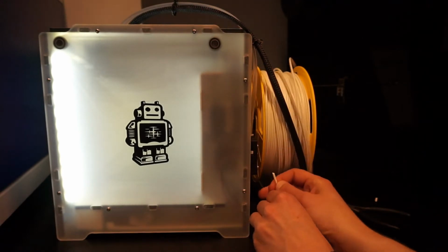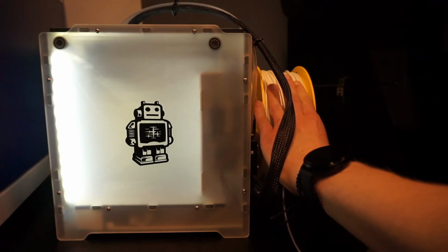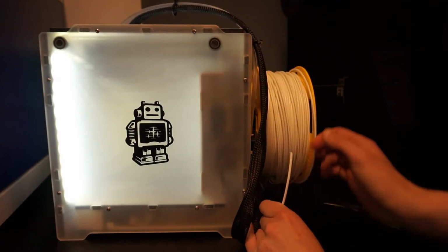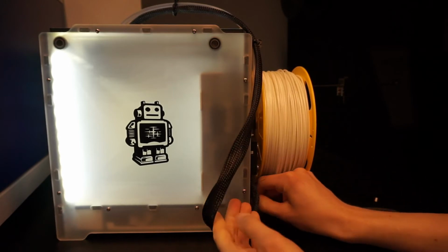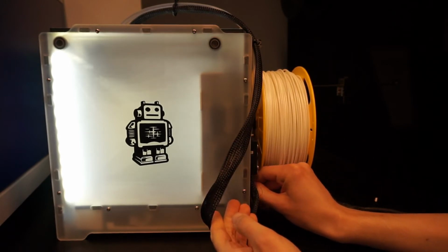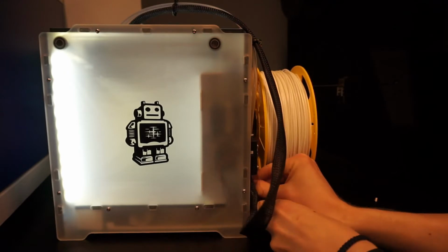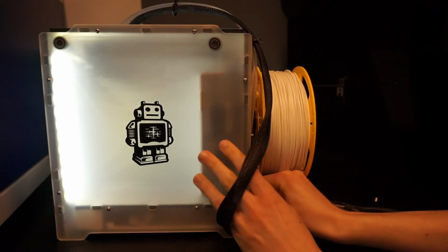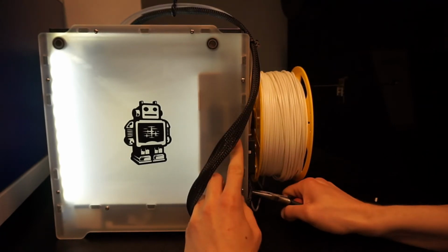You can now insert your material. You should be able to see a small wheel spinning in the tiny black box on the back of the printer. The trick is to insert the material in such a way that the small wheel grips the material and pushes it in the see-through tube. This requires quite some force and you can use pliers to help you.